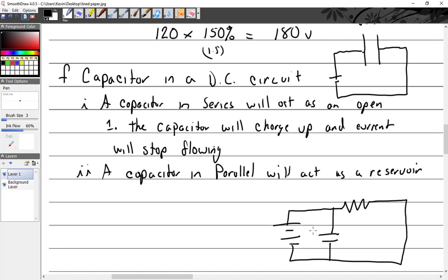Okay, so what happens in a situation like this is we could change this to maybe a light bulb. Here's a light bulb. As I flick it on, the light bulb has a higher current draw when it's first turned on until the bulb starts going. So there would be a bigger draw on the battery until it got going. This capacitor would feed in extra electrons to compensate for the sudden need, and so it would smooth out, acting as a kind of filter or reservoir.